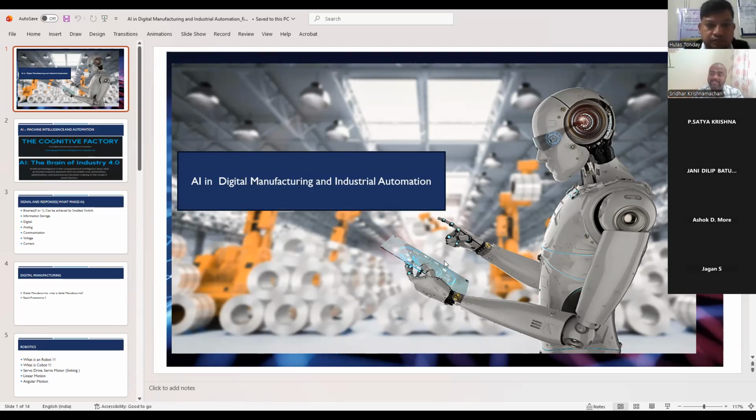Separative technology comes from machining, milling, grinding, coolant, a huge process, and it requires time, accuracy, precision, everything. But here you can get the drawing directly from the customer for the piston, or else design a piston directly. One advantage in additive technology compared to separative technology is you don't need to worry about the accuracy, because it will be developed step by step, layer by layer, micron by micron. Even for metal also it is possible.